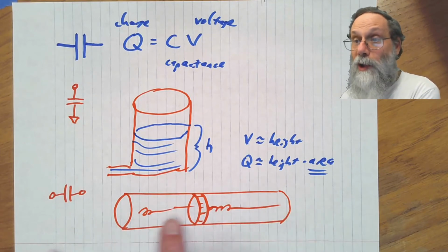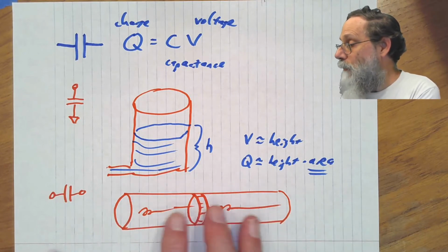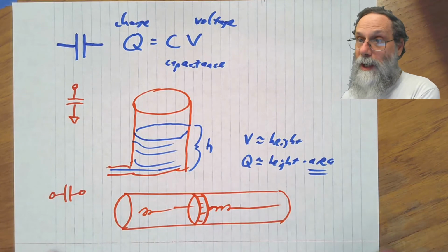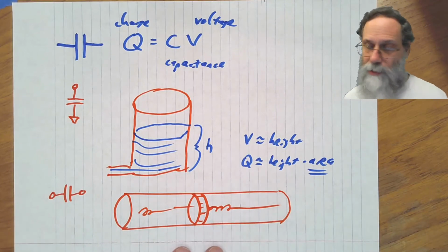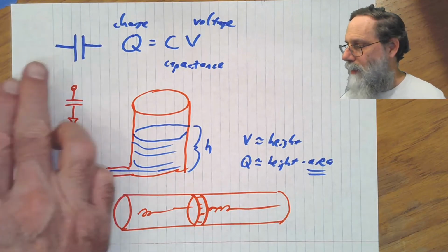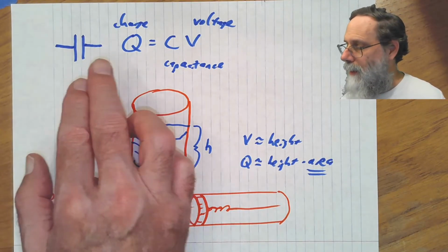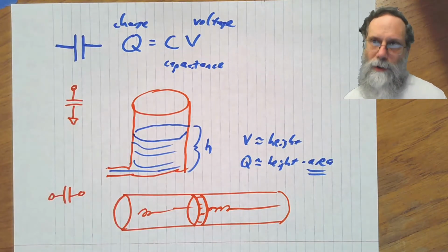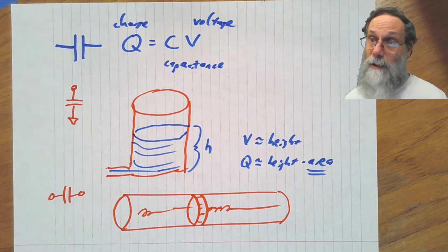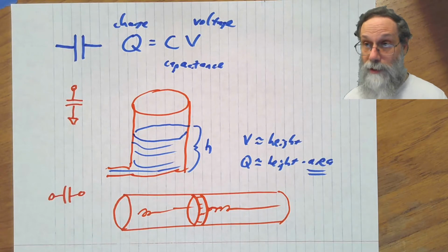It's not a direct current, but I can get movement of water that starts on one side and comes out the other side. And we'll have the same effect with capacitors. We won't be able to get a DC current through them, but if we put an alternating voltage on one side, we'll get an alternating voltage coming out the other side.